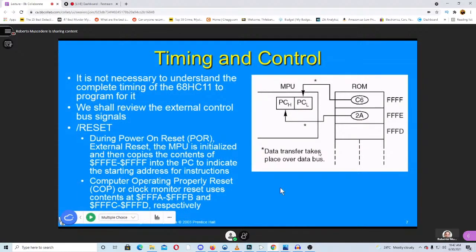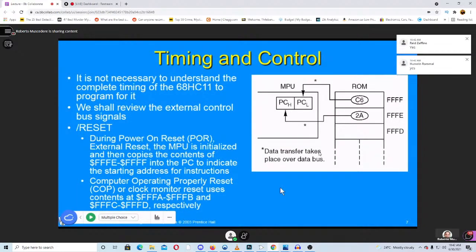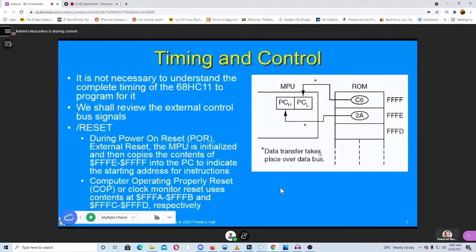Has anyone here had to reboot their internet router from time to time for no apparent reason, other than those things just weren't working, so you rebooted your internet router? And you couldn't just hit a reboot button, you had to unplug it and plug it back in. I'm seeing a couple of people say yes, because with those little power adapters you put in the wall, if there's a dip in power, maybe all of a sudden your device isn't getting 5 volts, it's getting 4.5 volts, and that 4.5 volts just happens to not switch a bit somewhere, and all of a sudden your system is somewhat tainted. And that's the worst kind of problem, because it's still working and you think it's working, right?